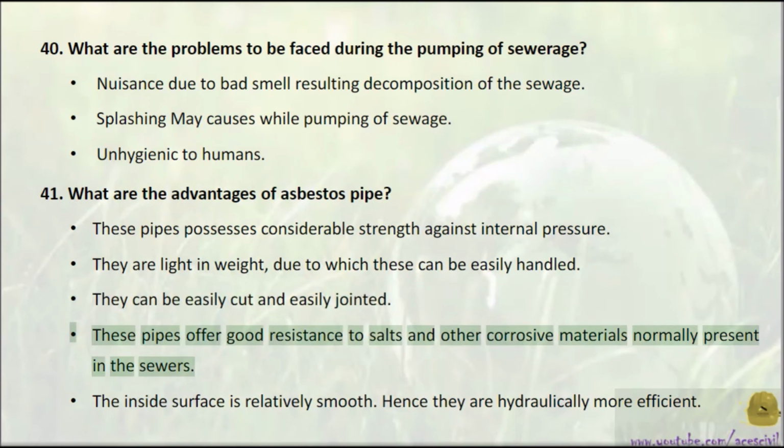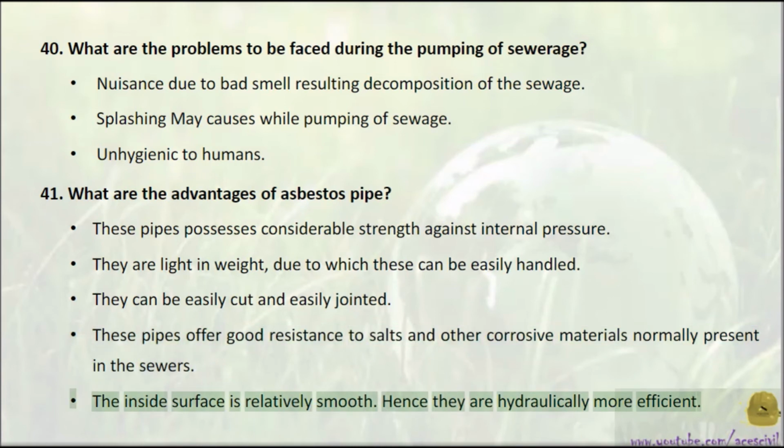These pipes offer good resistance to salts and other corrosive materials normally present in the sewers. The inside surface is relatively smooth. Hence they are hydraulically more efficient.